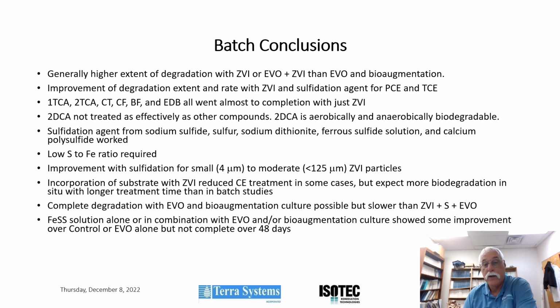Complete degradation with EVO and bioaugmentation is possible, but often slower than ZVI plus sulfide plus EVO. And the ferrous sulfide solution alone or in combination with EVO and bioaugmentation culture showed some improvement over the control or EVO alone, but wasn't complete after over 48 days.